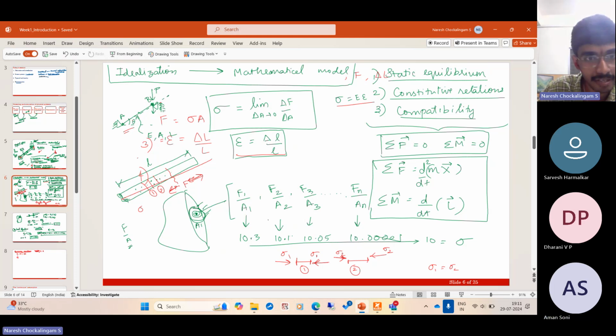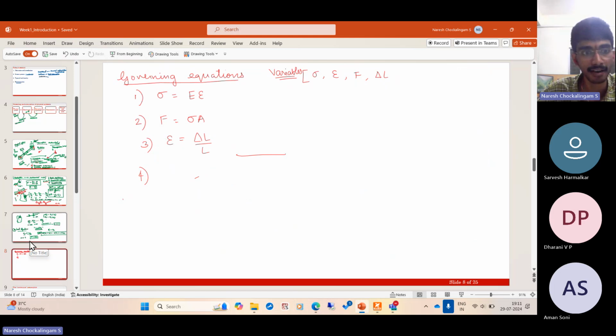That is okay if I put this as a hinge, but this is a hinge with roller, right? When it comes down, this net elongation will actually change. Since you have a roller, take the extreme case of a highly nonlinear deformation.